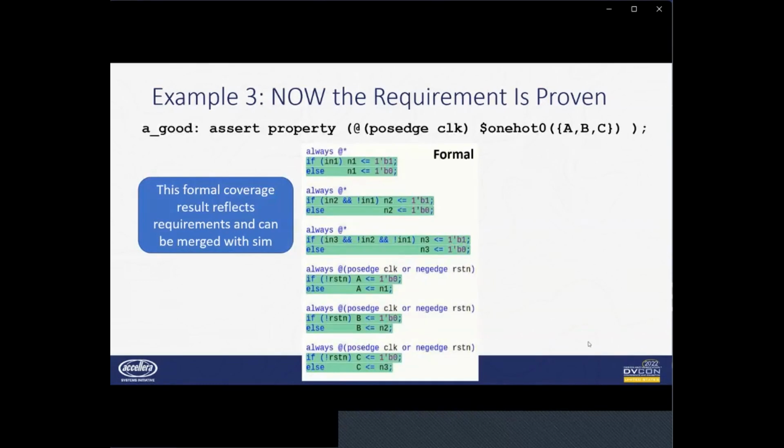to maybe take a look at boundaries, instance boundaries. As part of your test planning, you're assigning different modules or different blocks in your design to be fully verified with formal or have major function verified with formal. And then as part of your test plan, you're not capturing simulation coverage in these areas, and then you're merging formal and simulation together.